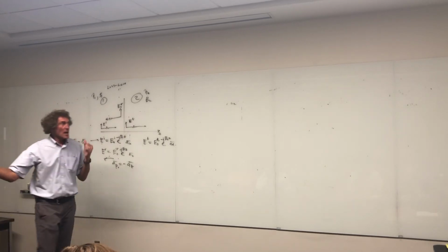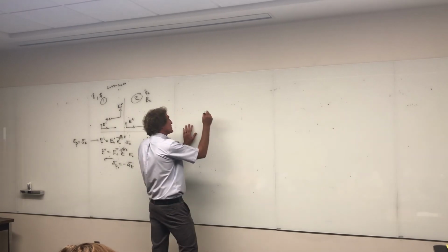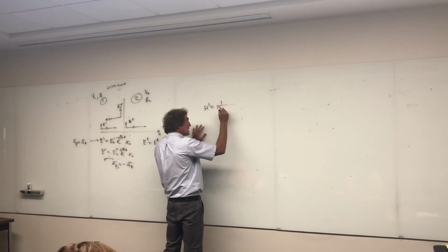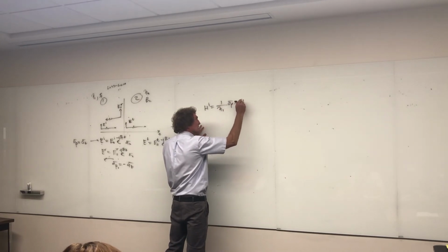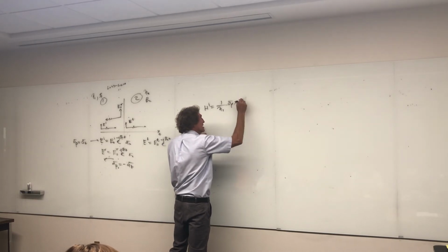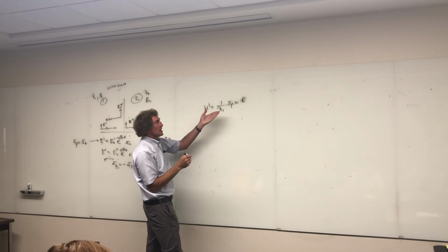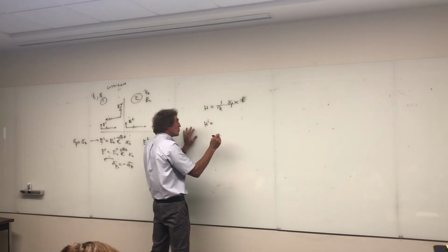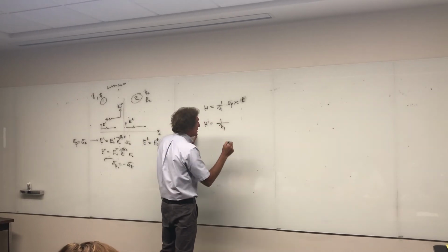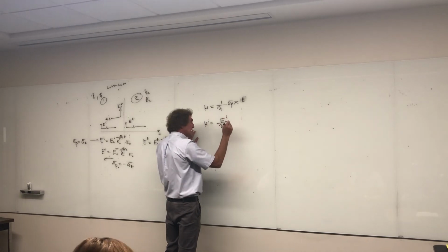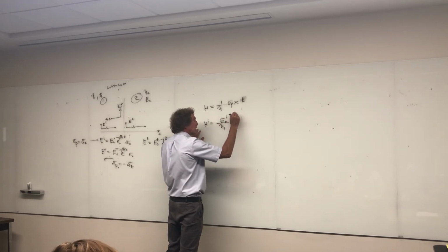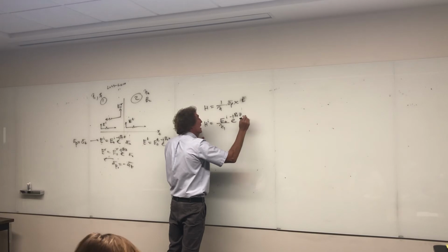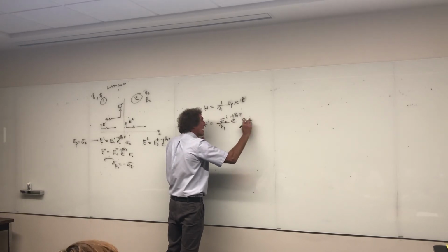Can you all see that back there? Yes. All right. Now, to get the H field, what do we do? Well, H incident would be equal to, I'm using the formula 1 over eta, in general eta 1, A rho crossed into E, pardon me. That's the general formula I'm using, 1 over eta, A rho crossed E. Let me just put it this way, make it general. So H incident would be equal to 1 over eta 1. And then I'm going to just tell you what the answer is. It's E naught incident, e to the minus j beta 1 z, ay, pardon me, ay.